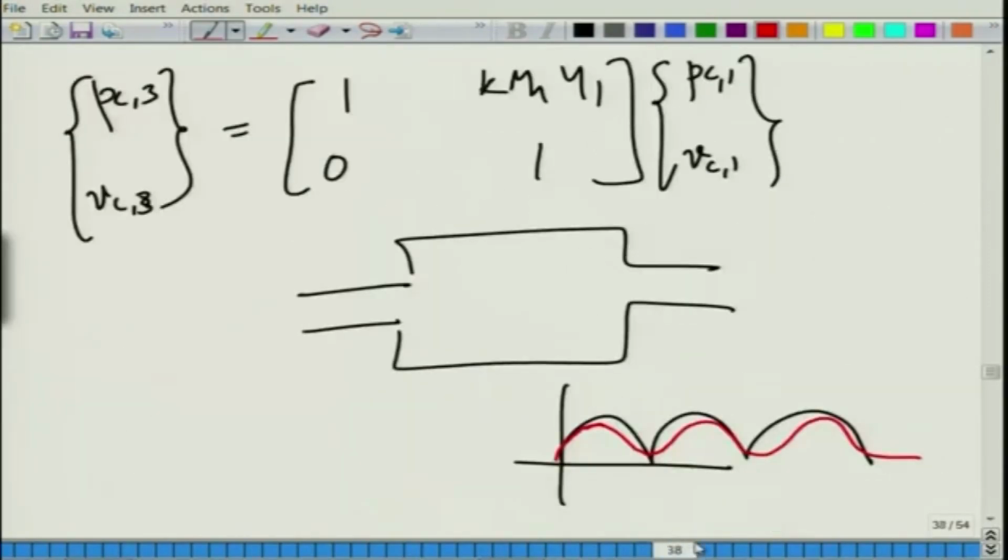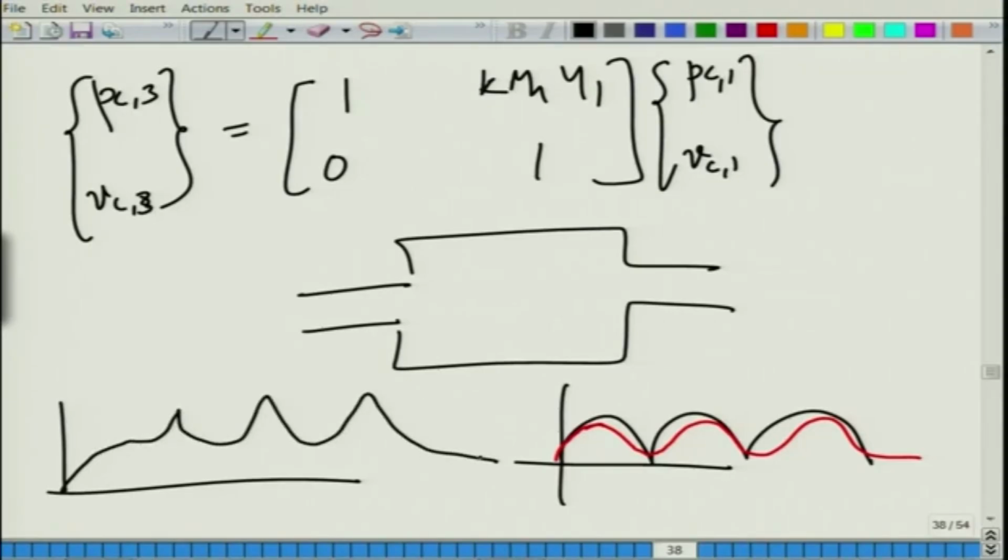So, for an extended inlet or extended outlet element, what one would typically imagine is that for a tuned element, the first order trough will be lifted, the second order trough will be lifted, the third one will be lifted, and so on. So, the flow will basically lower the troughs, and these will go up. Wherever there is a trough, it will try to lift it up. So, it has a smoothing or leveling effect, but typically these are all predictions without really considering the flow induced noise at the expansion, that is here, or at these points like I was mentioning.